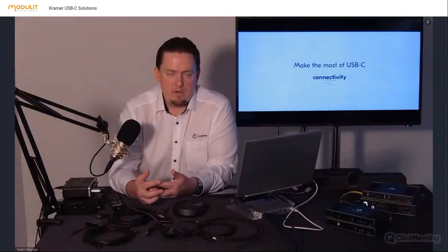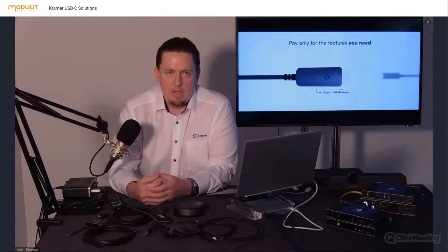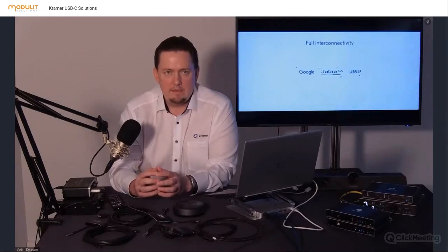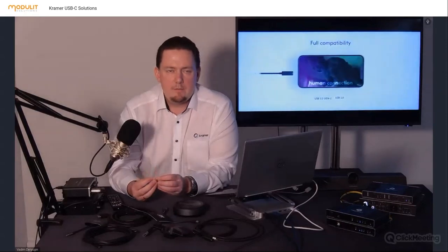Then we have the number of connections, because the old USB cables had only 4 pairs, only 4 connectors, 2 for power and 2 for data transfer. Data transfer in one direction and in the other direction as well. So today we have 24 connectors in the USB Type-C connector, and all of them are made to stand for their own operations. So if you need, you can implement some multimedia into the USB cable, and it's widely used in computer technologies.